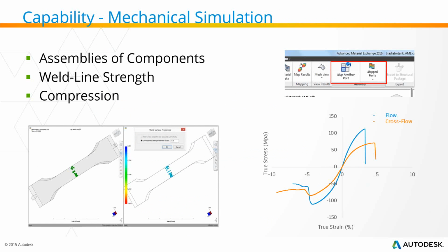In the last release of Moldflow, we were able, for 3D models, to capture the position of weld lines and where the weld lines ended up. We're now also looking at extending that capability to capture the temperature history and the pressure history of those weld lines as they were formed, and do an assessment of the weld line strength at that time.